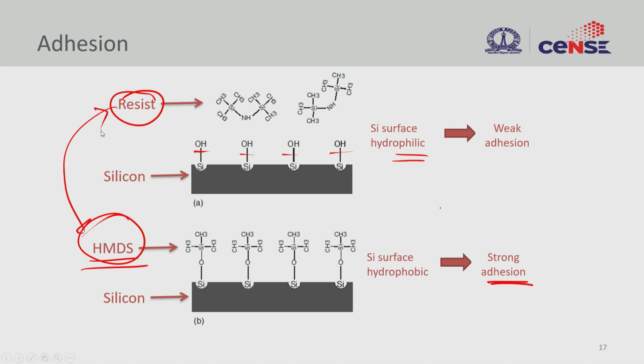So make sure when you are choosing a certain photoresist, you also choose the right adhesion promoter. You have this prescription from the photoresist vendor, and you can also look it up in the data sheet of the photoresist to see what kind of adhesion promoter one can use. There are some generic adhesion promoters, like HMDS, which is again a very commonly used adhesion promoter.